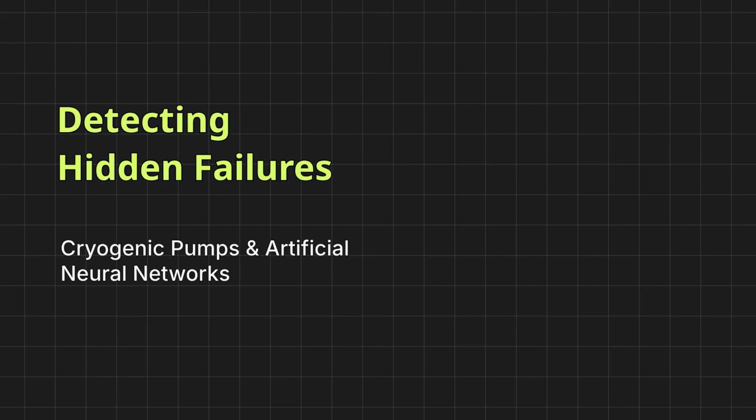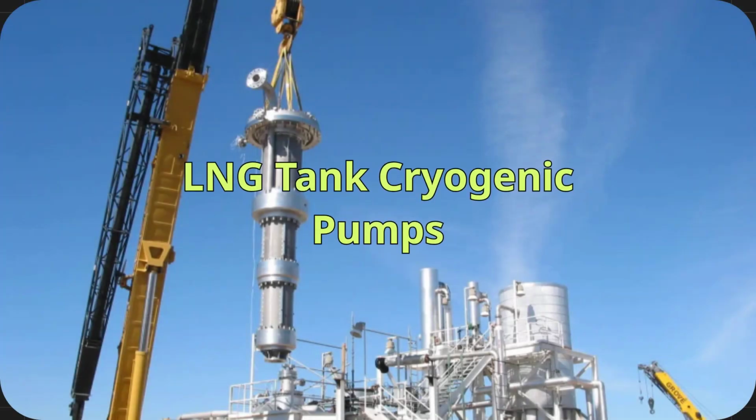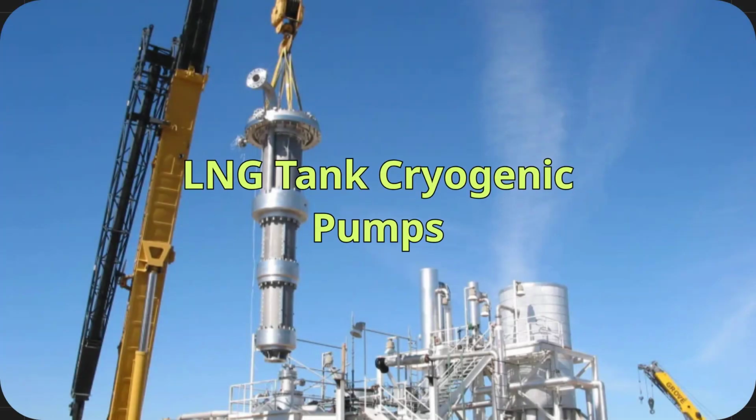Detecting hidden failures in cryogenic pumps by combining artificial neural networks and simulation. LNG tank cryogenic pumps are installed vertically inside a storage tank, with the suction foot valve positioned at the bottom. This design eliminates the risk of major tank leaks caused by issues with pipes or connections. Both the pump and motor units are submerged, with the column serving as a guide during installation and also functioning as the discharge pipe that channels the pumped liquid to the top of the tank.